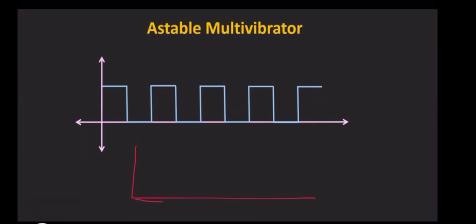be a stable state and another will be a quasi-stable state, so that you can generate a pulse width of a required duration. Whereas in case of astable mode, both the states are quasi-stable states. There is no stable state in this case. So using components, you are generating a square wave at the output. Or even you can vary this with respect to the t value by designing.